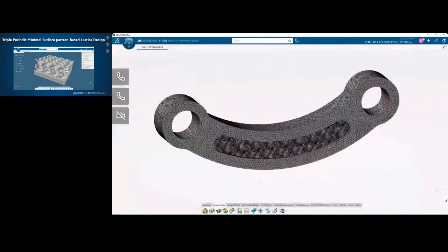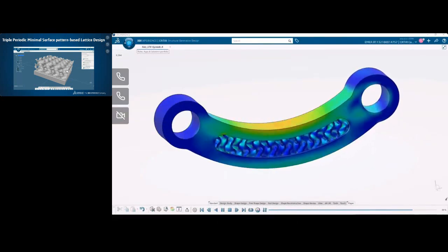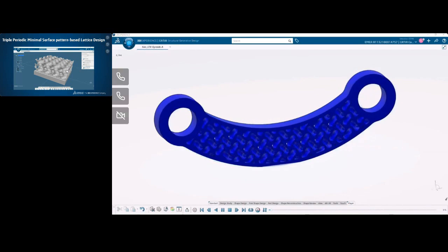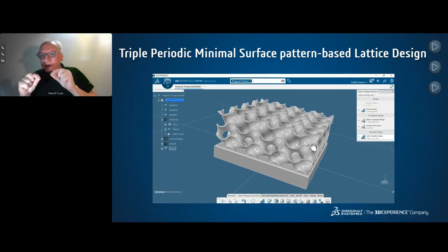And you can run any type of simulation where you need those tetrahedral elements. Okay? This is also possible. So you are not forced, again, to work, for example, with a 1D beam for the cylinders, but you can also run a tetrahedral mesh inside the cylinder, depending on the actual physical phenomena you would like to simulate or validate. Can we launch the second video?